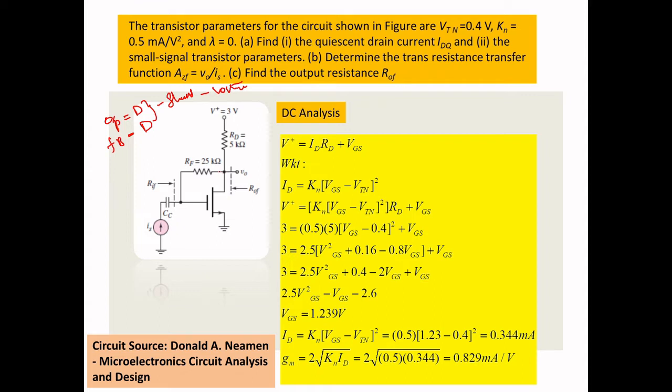Observe the circuit clearly. The feedback is connected to the input directly at the gate. So that means there is a mixing part, and the mixing part will be a shunt. So that means voltage shunt feedback circuit.